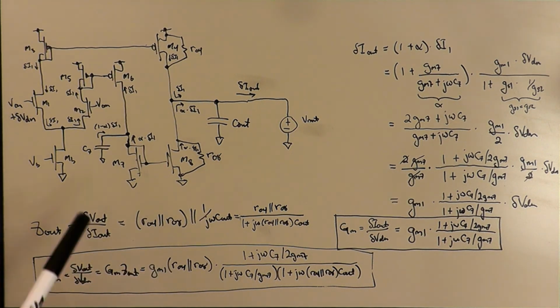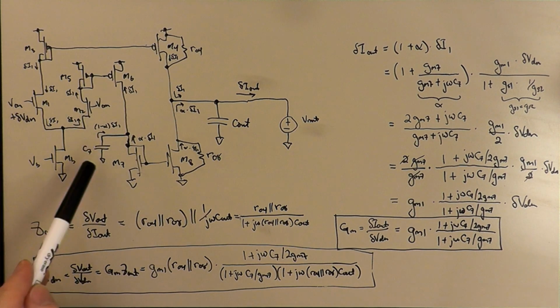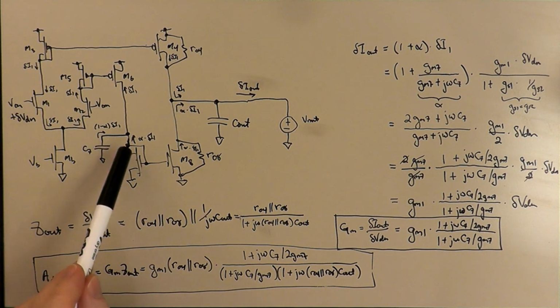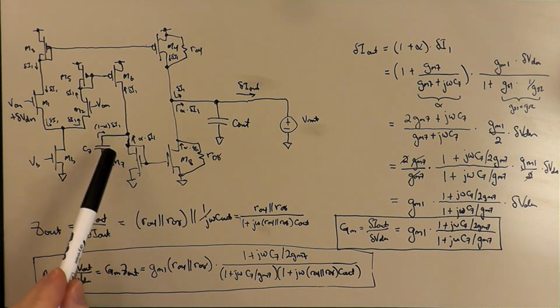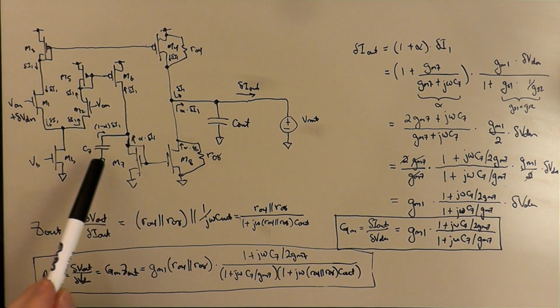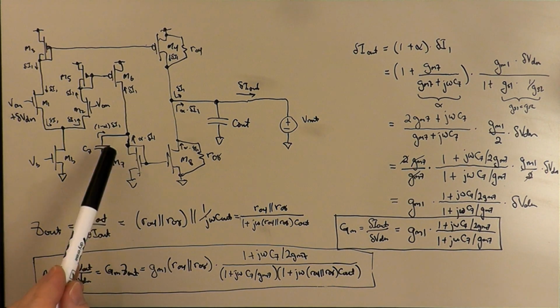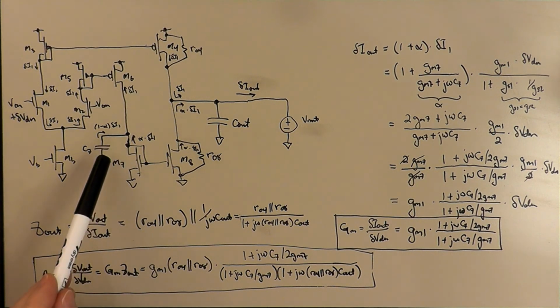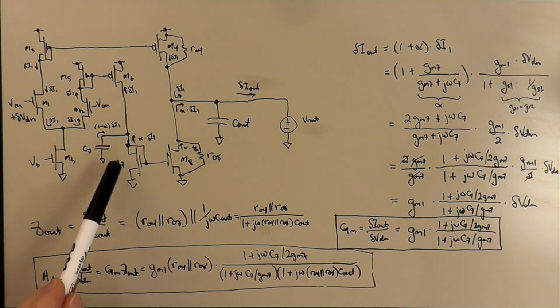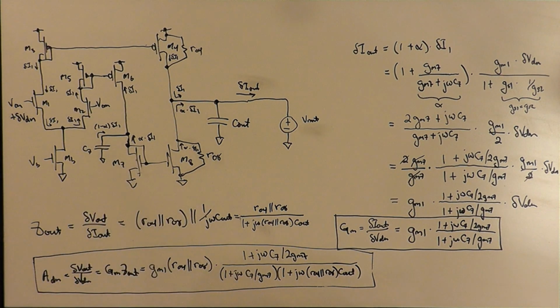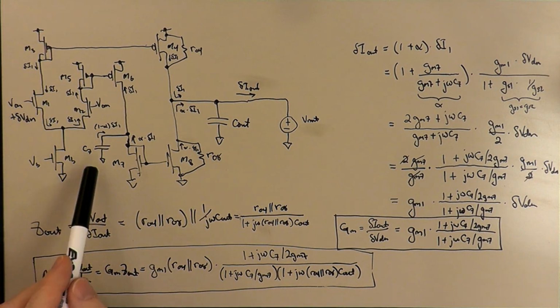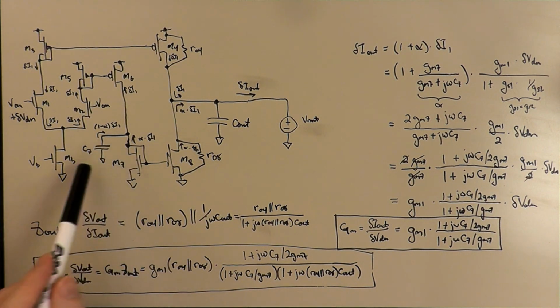Okay, so in general, adding these capacitances in basically introduces extra places where current can be shunted away, and you pick up additional factors of current dividers, current divider ratios, as you kind of chase these current increments through the circuit. And so you can kind of ask yourself, at what frequency would this capacitor kick in?